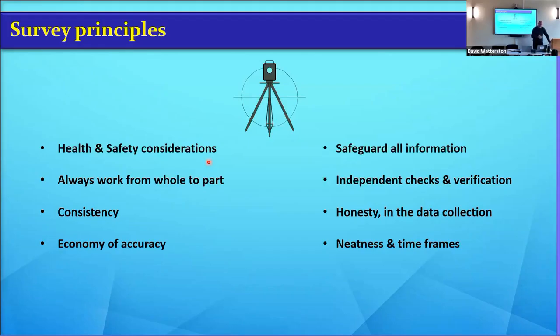So you've got to look at trip hazards. You've got to look at if somebody throws a brick out the top of a building and hits you in the head, the hard hat may have saved you a little bit anyway. And even at that, you've got to look at hard hats because the sunlight destroys the plastic and makes it brittle. So think about that.